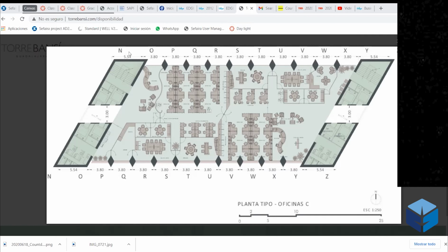Okay, so we're going to use this plan, and instead of using these funky measurements, I put it easier for you. This is going to be a 6, and the total is going to be 50. That's only to make your life easier. We're going to round up things. Okay, so we're going to be based on this plan, but it's not exactly that plan. We do have these columns on the facade, and that's going to work for the window-to-wall ratio. That means that from this facade, let's say this is the south facade, to calculate the window-to-wall ratio, you have to take out this part of the facade, because it's not counting as window, and all this part of the columns. You see? The rest of that is going to be window, so that is going to count as the window-to-wall ratio.